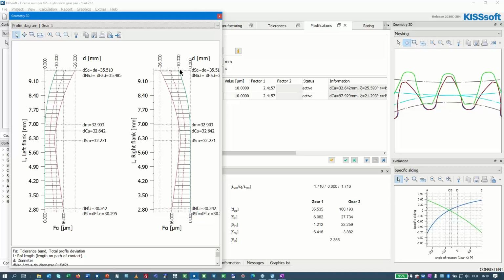Again, if you assume random errors over the thousands of plastic gears you manufacture, the average error is 0. This means you will see a shift in the manufactured gears towards a 10 micron tip relief.